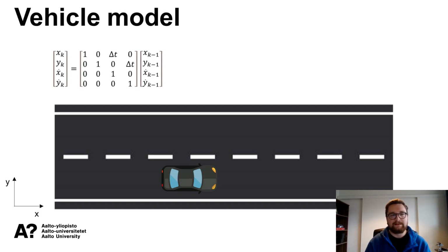There is no flexibility in it, because naturally the car accelerates as well, so the speed is in fact changing. So our model is not very accurate this way, and there is of course all types of other noise in it as well. So let's try to model all these noises, most specifically the accelerations that are happening with the car, by just putting this vector q here.